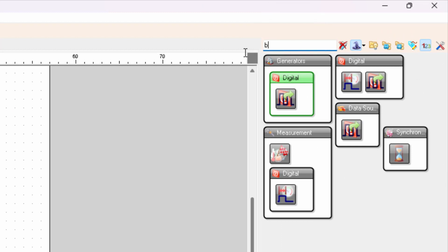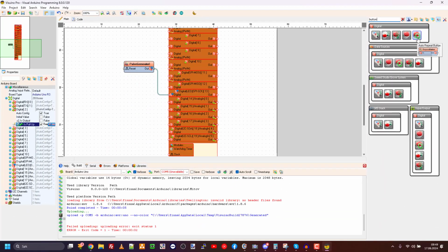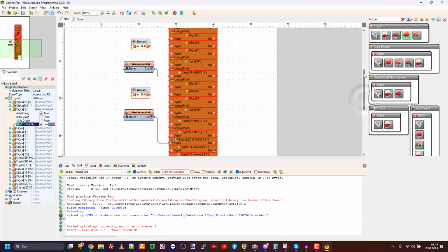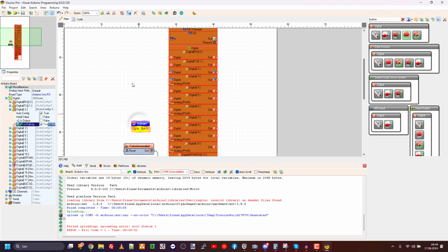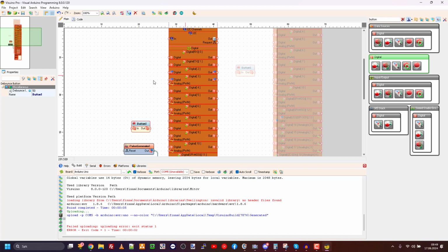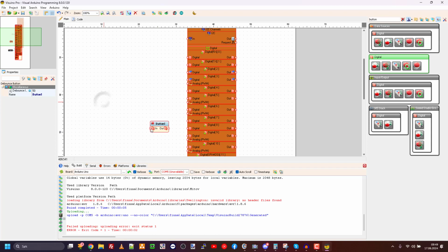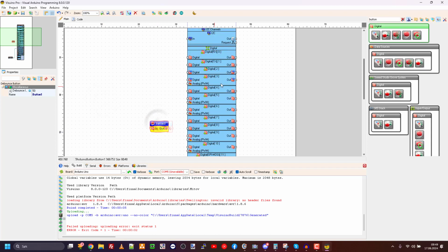So in real projects, when you click the button, there can be small sparks, so that the input can go high and low very fast. So we will use a debounce button, and that will ensure that it has to be some time, like 50 milliseconds, to ensure that it's only clicked once. Some switches, when they're becoming a little bit bad, can give you 2 or 3 clicks in each press.